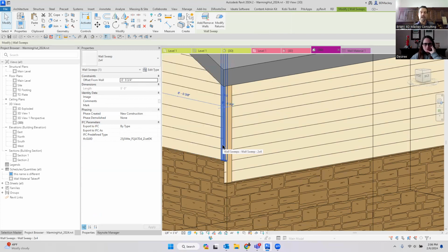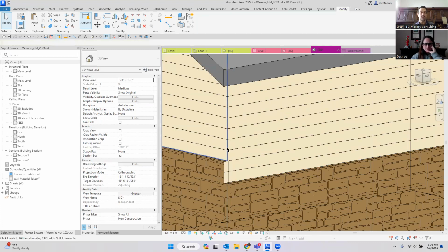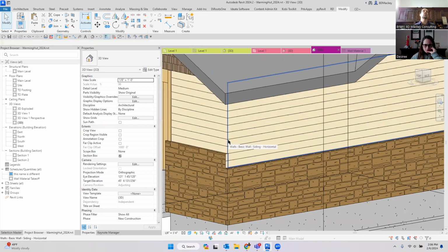If I wouldn't have had trim on this outside corner and these were stacked walls, I probably would not get these walls joining in the corners. They do so many horrible things that in my entire 20 years using Revit, 22 years using Revit, I've used stacked walls twice. Too many combinations. They cause issues. You're not in any control of how any of the cleanups or anything work. It's just not a big deal.